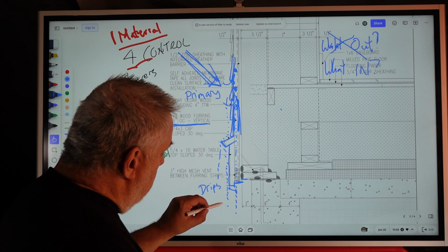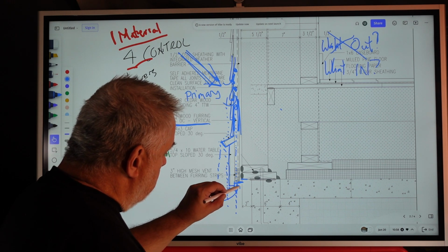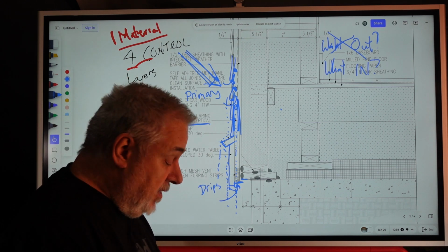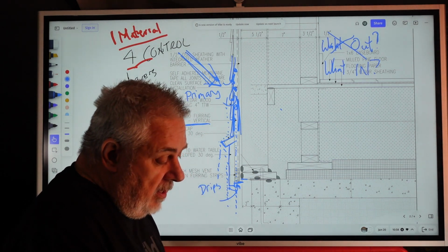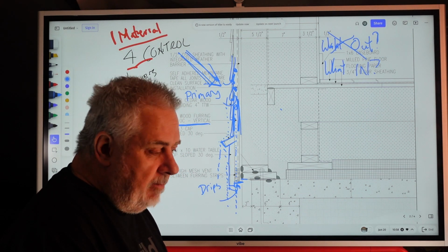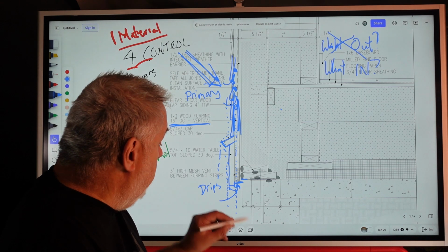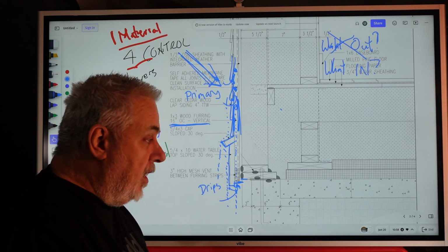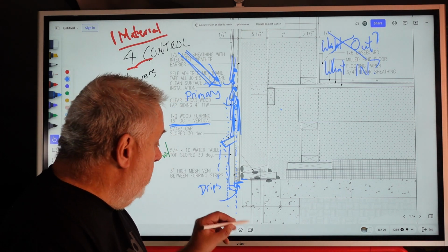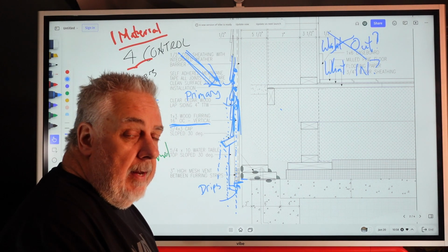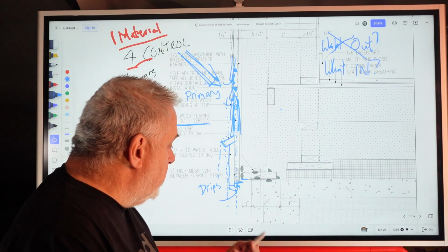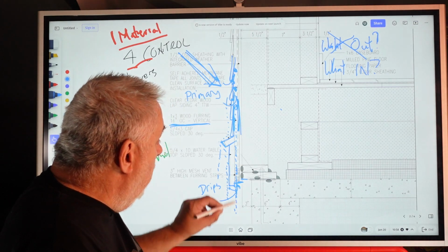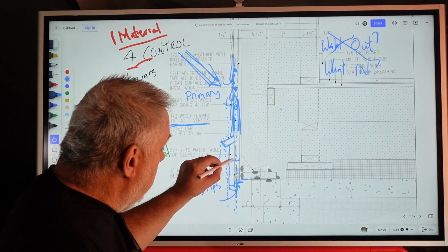The mesh there is to keep the migration of bugs, which I'm still on the fence about, because they just do not like that space. I know it's a hard one to believe. You're going to tell me all kinds of critters are going to get up there, but they don't. They don't like it. But anyways, we have our venting strip. Core Vent makes it. Cobra Vent you can cut. There's a whole bunch of options, you can put bug screen and staple it over the furring strips, whatever you want. But the ability to get that water out, and that's a 3/4 inch space.